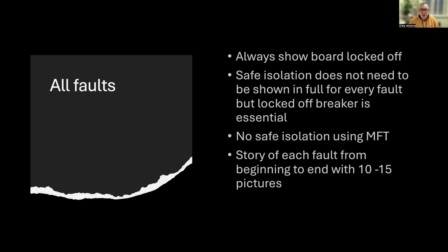No safe isolation using a multifunction tester. That's a voltage indicator only. And it's a voltage indicator that complies to GS38. Look at paragraph 19 of GS38, and that'll explain to you why. And each fault, story of fault from start to finish. So 10 to 15 pictures. I put 8 to 10 pictures, or 8 to 12 pictures, just showing the event of what happened. So we've got full story from start to finish of each fault.